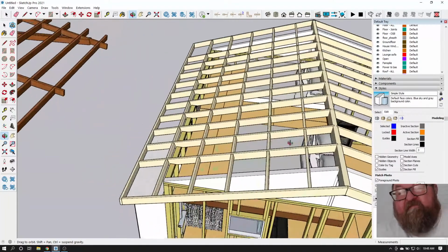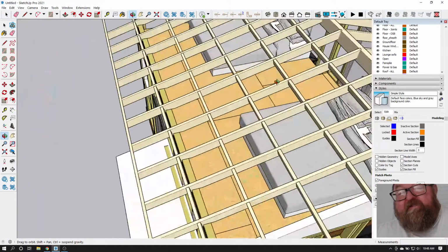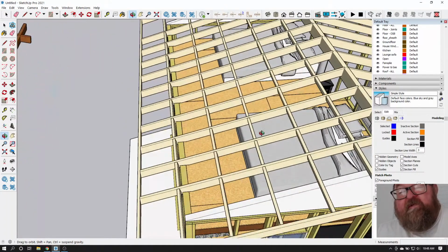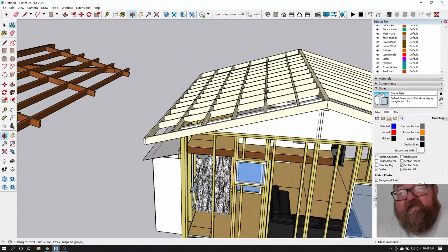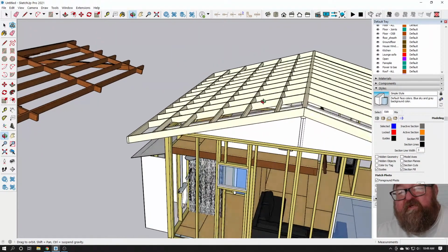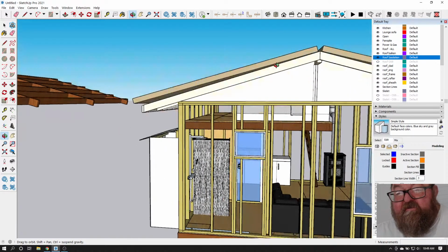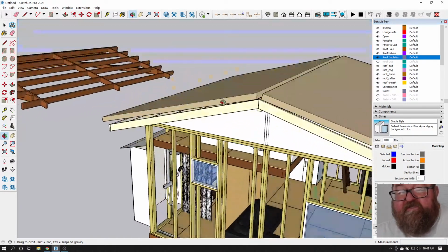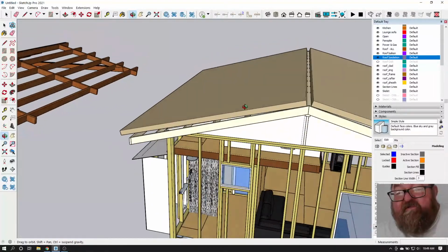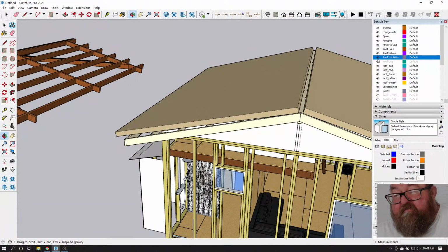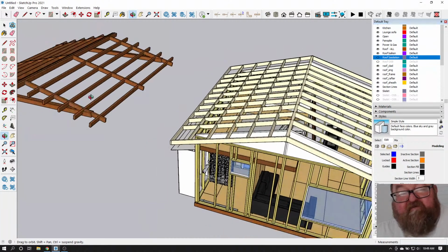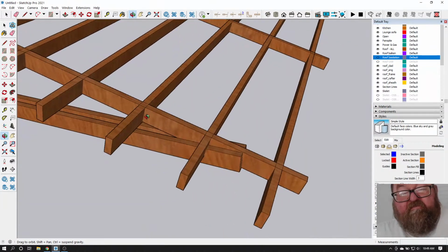So, if all these members get bigger, they get farther apart. Okay, so if you think these spaces are too small, then the other thing I haven't mentioned is that he's doing a warm roof. In other words, the insulation goes on top. I wonder if his insulation would fit on top. Yeah, almost. It's almost the same pitch. But the insulation goes on top of that and then his roofing material. So I'm just having to kind of assume that